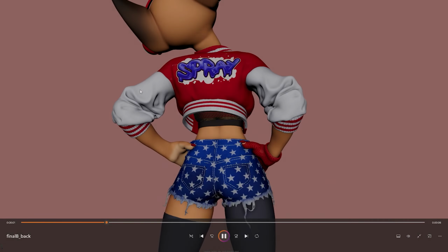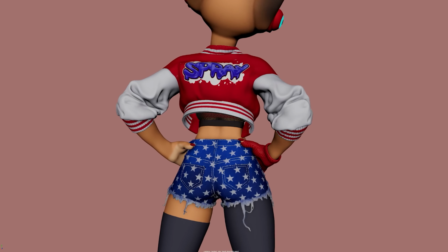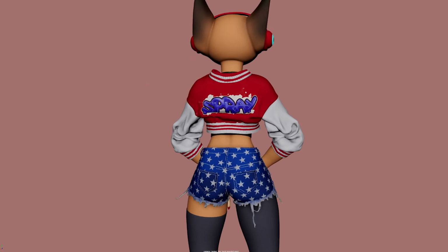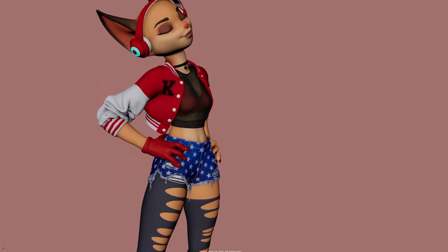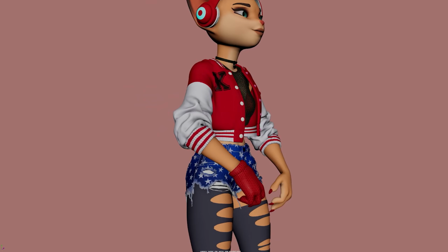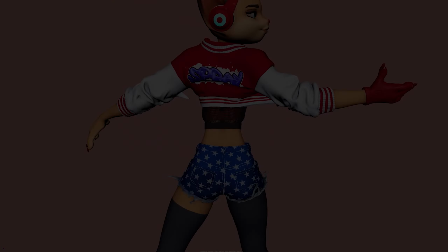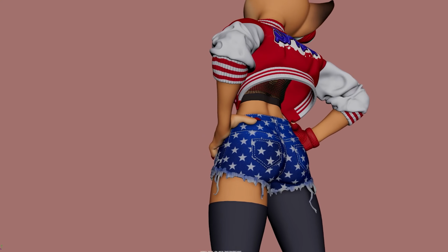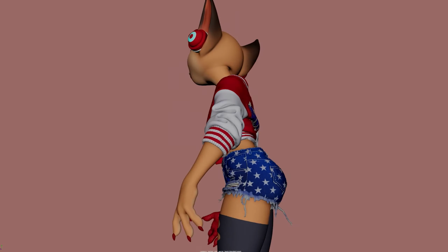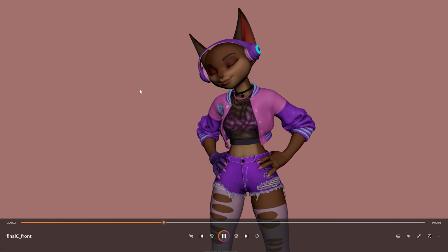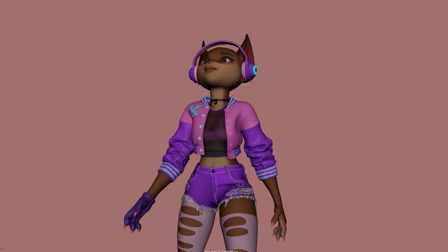I needed something that produced believable cloth for a stylized character. And at the same time, I wanted the most amount of control, even if it meant defying the natural behavior of the specified materials. So you watched me set a lot of unrealistic values for nCloth properties and do a lot of weight painting to make my nCloth behave uniquely in certain areas.